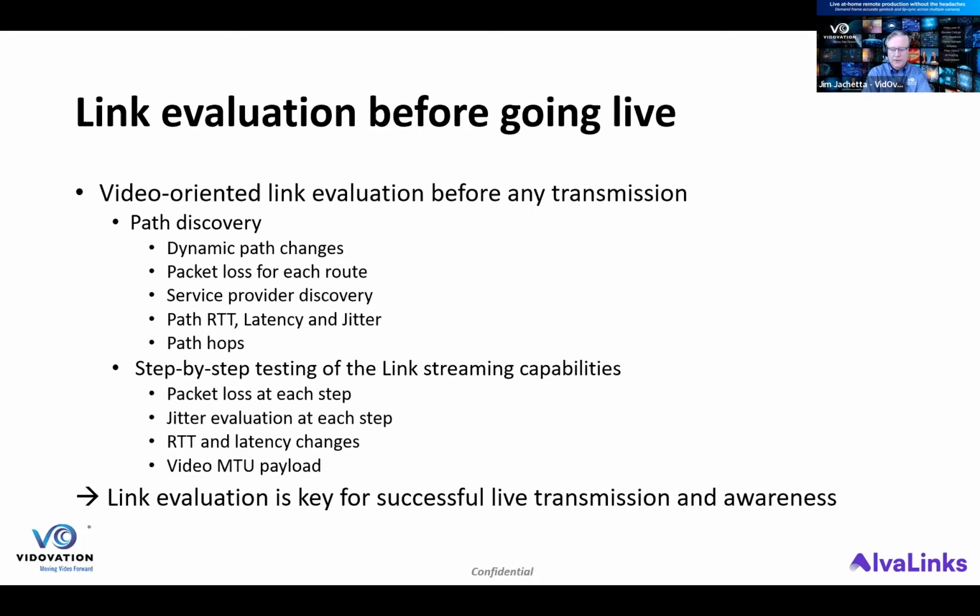This is a good point, and I know from my bonded cellular experience that a cellular connection, typically with 5G, is improving. With 4G LTE, 40 to 60 milliseconds is a typical connection, but there will be these unexplained spikes, 1200 milliseconds. Exactly. But it only occurs for a split second, so you see these spikes.